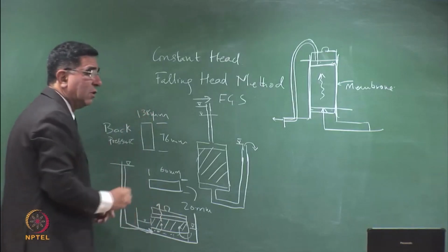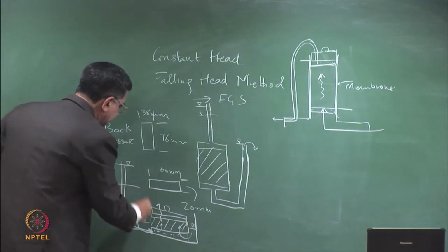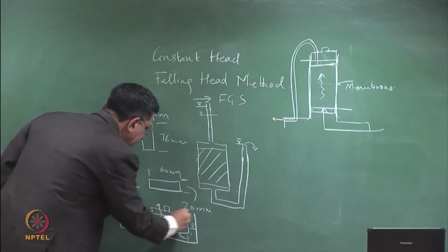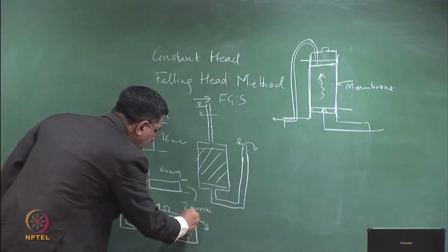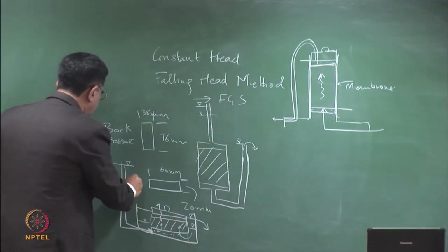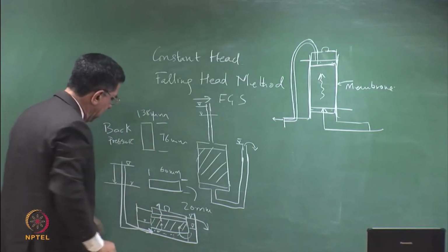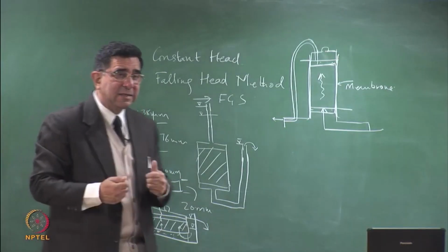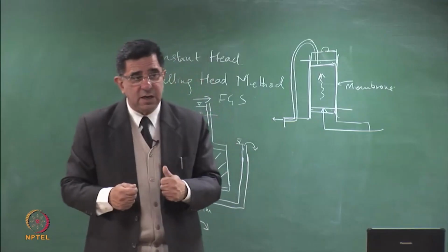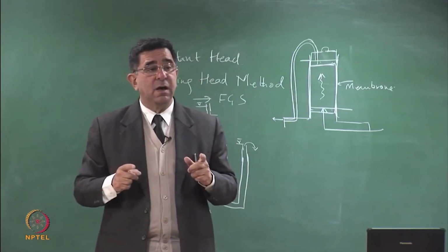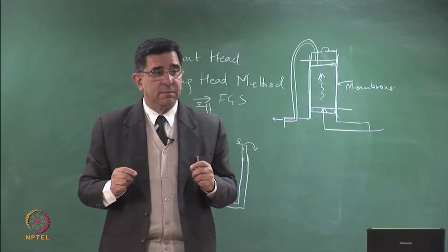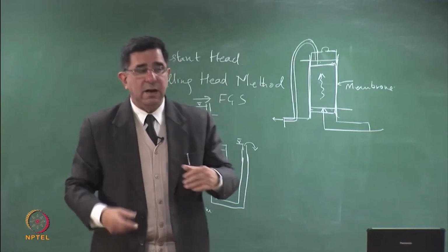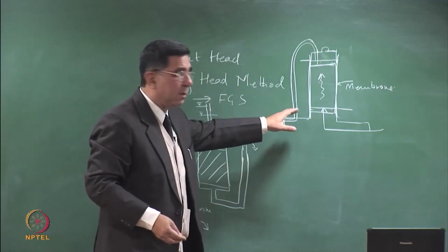Then I can get the water to come out. But this will be done like a falling head test. So the water level will be increased by us to this level, and this will allow overflow, and my head will fall with time, and the flow will occur bottom upwards. So you can use a direct measurement in a consolidation cell, but this is a rigid wall permeameter. Rigid wall because the ring is rigid, and this is a flexible wall permeameter.